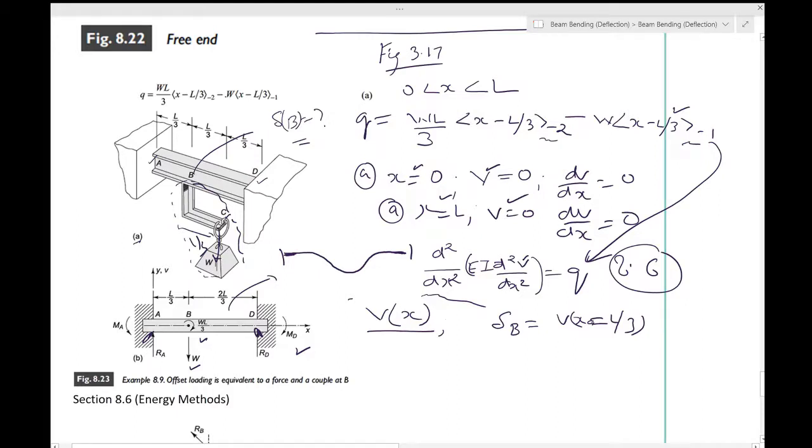So one of the things is, I think the deflection of a beam should always be reported as a positive value. But this v of x will always throw you a negative number, because the beam is bent like this, and displacement is in this form. But the deflection as such should always be reported as a positive. It's just a practice. You are free not to follow it, and you won't be penalized for it, at least in this code.